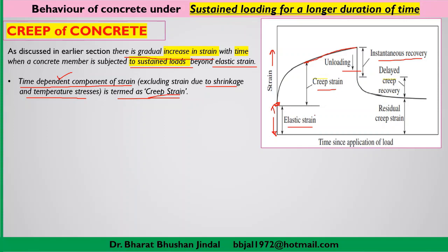So first of all we have gone through the elastic strain, then the creep strain, and after unloading there is instantaneous recovery. After this instantaneous recovery, it will take some time to recover the creep, to reach its initial stage. This is known as delayed creep recovery, that means it is not instantaneous, it takes some time.